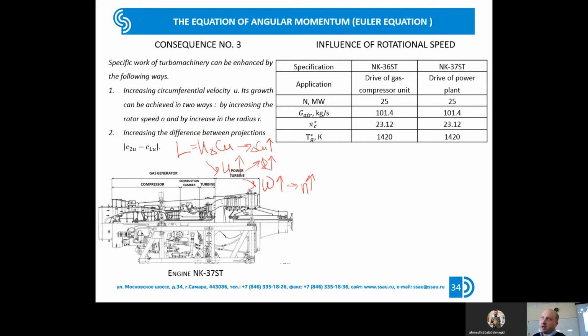The nozzle, afterburner, and mixer were removed. This part was taken mostly from the initial engine NK32, and it is called the gas generator. At the outlet part of the engine a turbine was mounted, which is connected with the energy supply system.